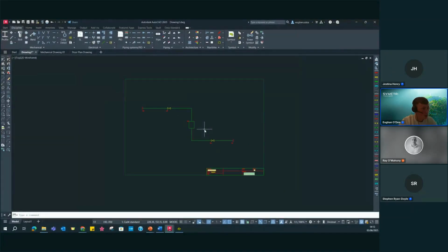So now the next thing I want to do is automate a task that can often be quite tedious, which is to create a bill of materials or a legends list or a parts list for this P&ID. So I can easily do that in AutoCAD, in Sovelia AutoCAD, sorry. So I can just choose from legends list. This will generate a legends list directly from my P&ID drawing, where we can see we have an icon for each component, a quantity, a brief description, and we have the option there to insert a location if we wish to.